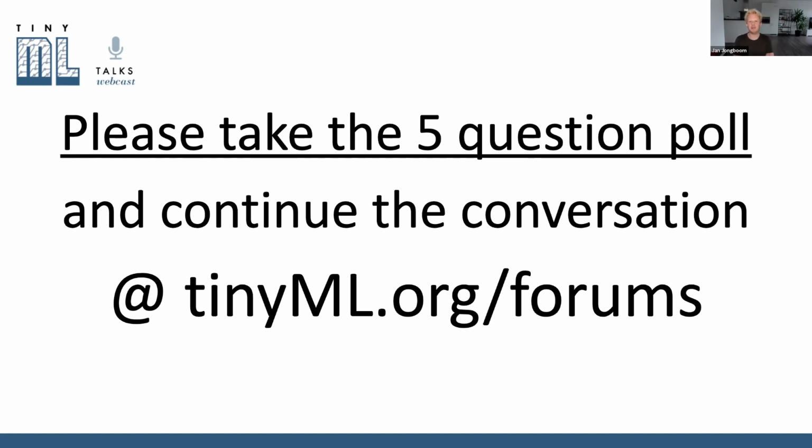However, with ML, that's also possible, right? If you're constantly listening to the audio channel and constantly doing inferencing, that is going to deplete your battery very quickly too. So then you don't win a lot. But we don't need to do that. We can take a look at camera traps, for example, where you typically have a motion sensor, and only when the motion sensor triggers, which is relatively low power, do we spin up the main MCU, snap a photo, classify what is happening, and then act on it.